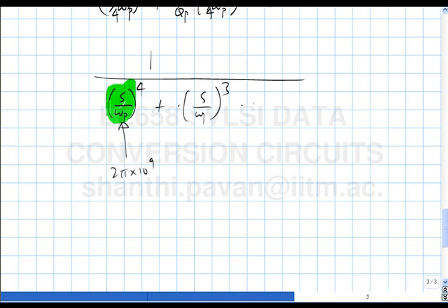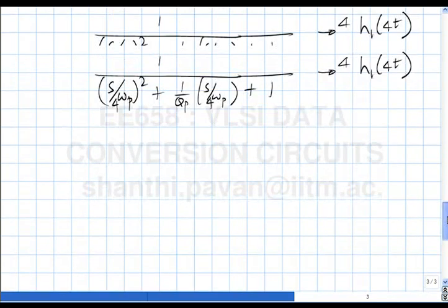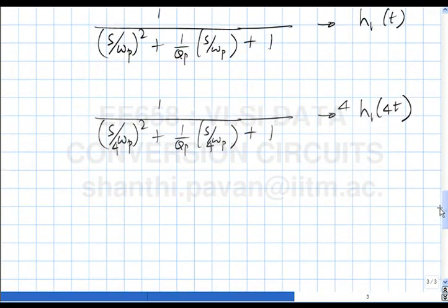So in all your delta sigma work, it also makes sense not to work with absolute frequency. You always normalize everything to the sampling rate, so that the sampling rate becomes 1 hertz. You do all the math, find the NTF coefficients, find the loop filter transfer function and all this stuff, and then you go back to the real world. You understand? I think it's better not to start the next topic. I will stop.